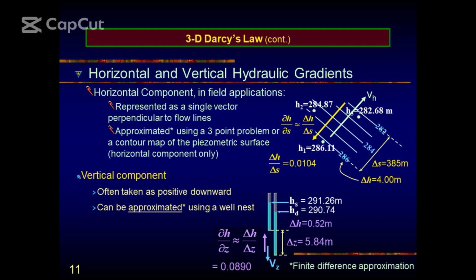And part of the reasons could be the entry losses. Okay? But the main thing that I want to emphasize is that water table could coincide with the phreatic surface. And sometimes it may not. So bear that in mind. And that could be due to the capillary fringe. Because water is almost saturated, yet not available. And the pressure in the capillary fringe is not atmospheric. It is under suction. Same as the pressure in the unsaturated zone. It's under tension. Negative pressure. That is below atmospheric pressure.